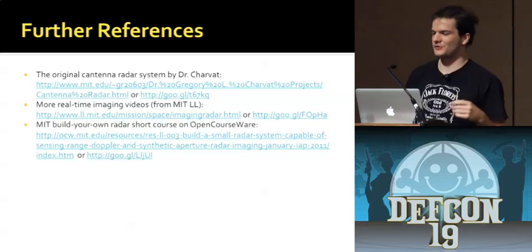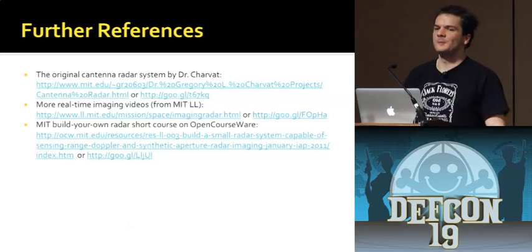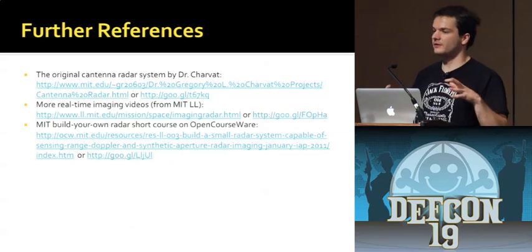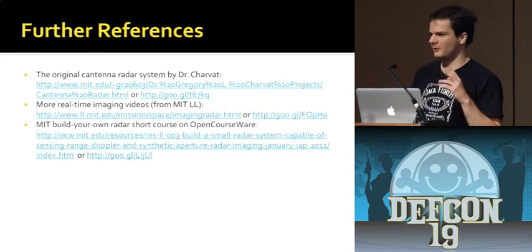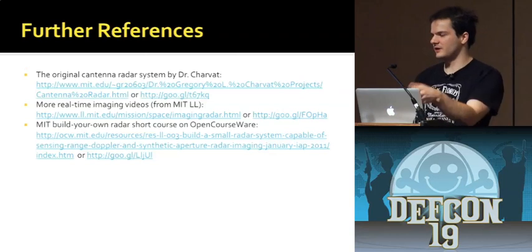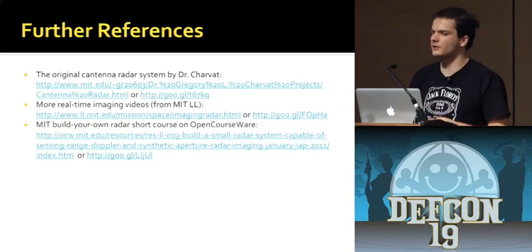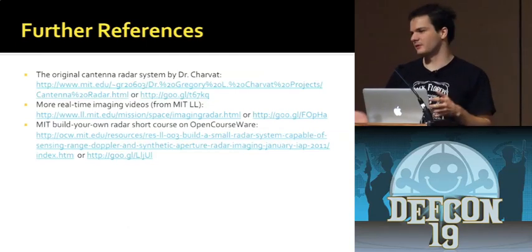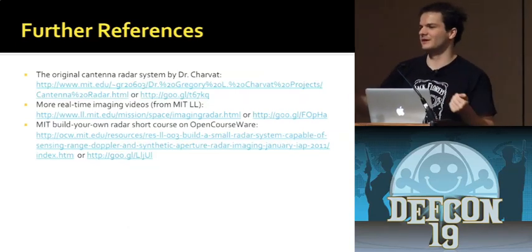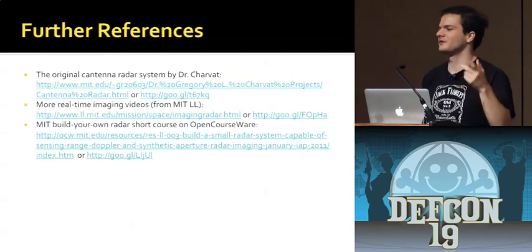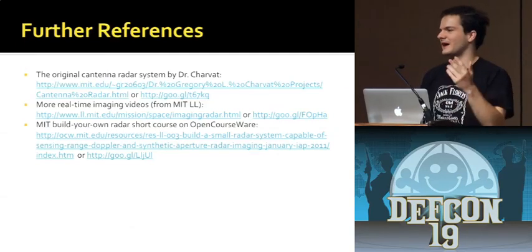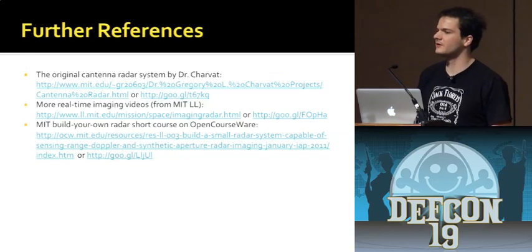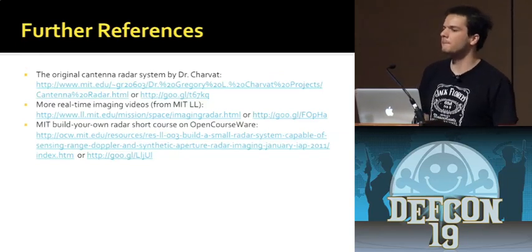He asked if I was looking at software-defined radio systems. I think there would be some benefit to that. Certainly the SAR coherent processing would benefit greatly from an FPGA system, because it can take a few seconds to process an image like that on the computer. But in this case, the main goal was simplicity and low cost. If you bring in one of those research boards, like the USRP or something, that's going to add a big chunk of change to your design. But there's definitely a lot of potential there. I would say that's absolutely worth exploring.